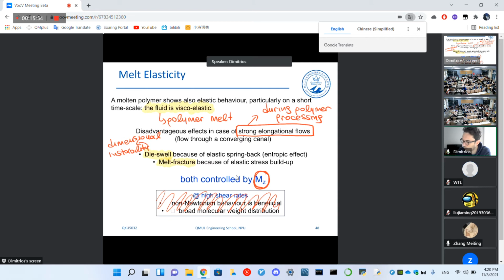So the longer the chains, the more opportunities there are for the chains to build up the stress. Because once they're mingled in the melt state, sometimes when they come out, because they crystallize, it's more often for them to form entanglements. So when the material comes out, essentially it forms entanglements and swells more.